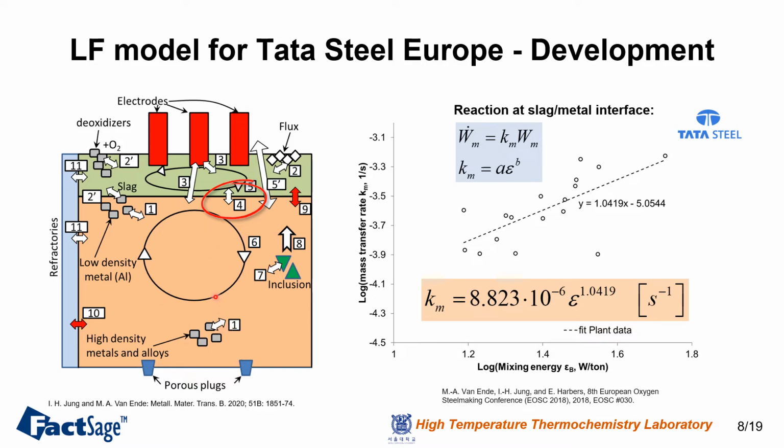And also, in order to control the temperature of the final steel, we are doing arcing through the arc on the top here, and part of the arcing heat can transfer to the metal, and part of it can transfer to the slag. So of course, we can also consider refractory dilution on the slag side, and also heat loss through the air and the refractory side.